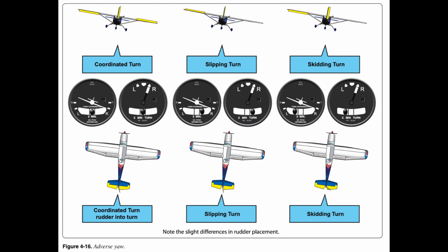Coping with the hazards of icing begins with pre-flight planning to determine where icing may occur during a flight and ensuring the aircraft is free of ice and frost prior to takeoff. This attention to detail extends to managing de-ice and anti-ice systems properly during the flight, because weather conditions may change rapidly, and the pilot must be able to recognize when a change of flight plan is required.